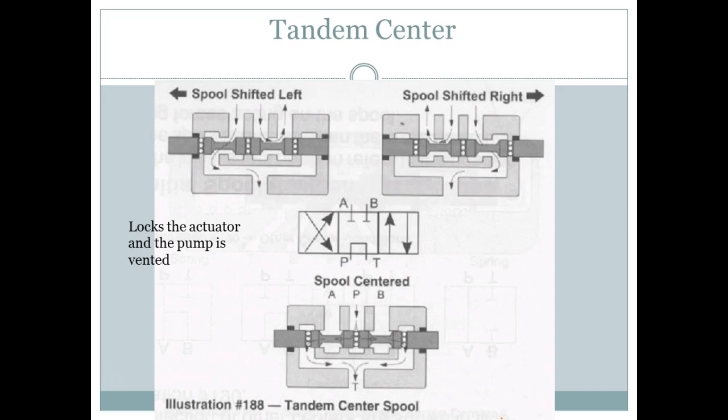The hydraulic fluids that they were using at the time had a lot of additives in it to add a lot of features that they don't do with mineral oil. And it was those additives that caused it to be so dangerous. So that was one of the reasons we decided at that point to get rid of our hydraulics, and plus it's messy. You cannot keep a hydraulic system from leaking just a little bit. When it leaks, it gets dirty, and you see dirt all over the place, and it's caked up.